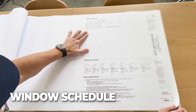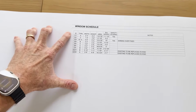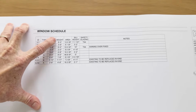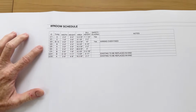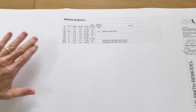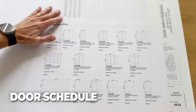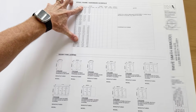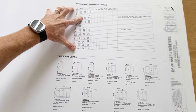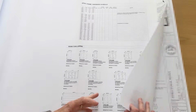Finally, we made it to our door and window schedule. As you can see here, guys, our window schedule is identified very simply. It talks about your width, your height, and any other specific notes that you have to pay attention to. This is where, earlier in the floor plan pages, these numbers are going to be found. Okay, so door and window schedule, door schedule. This does interior doors as well as exterior doors. Again, it talks about all of your heights and your widths. We want to really pay attention to this when ordering and making sure we're framing for certain openings, all right?